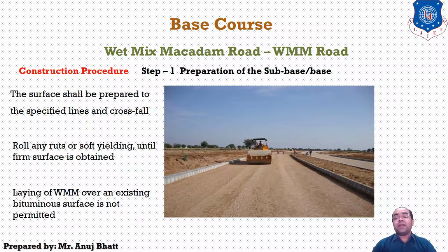Now, laying of wet mix macadam over an existing bituminous surface is completely prohibited. We are not permitted to apply the wet mix macadam over an existing pavement. If we need to provide a surface, then for that we can use the water-bound macadam road, but we cannot apply the wet mix macadam over the existing pavement. Okay, so whenever we are preparing such courses, we have to deal with the compaction. During the compaction or after the compaction, if you feel the surface is very dry, you can apply water by sprinkling, and that sprinkling should be copious, or we can say the procedure should be homogeneous.